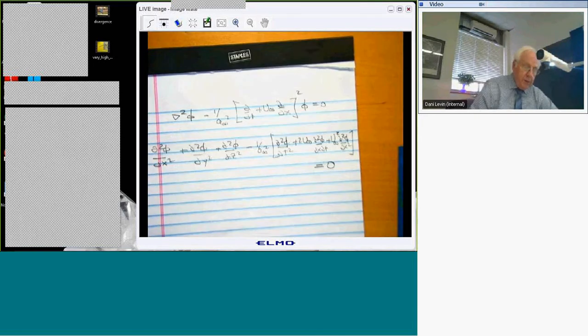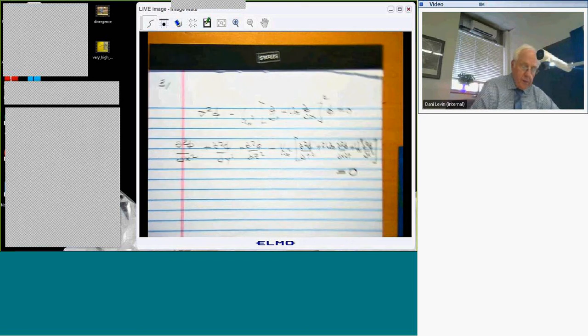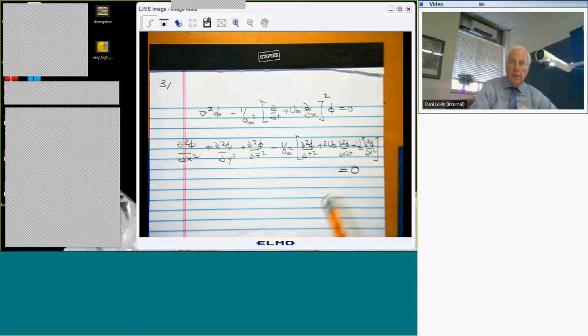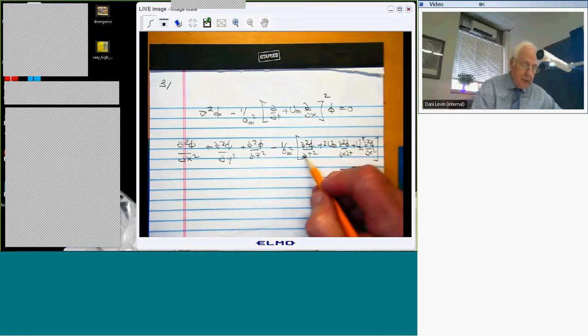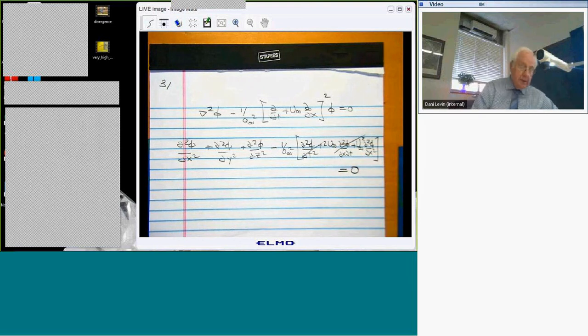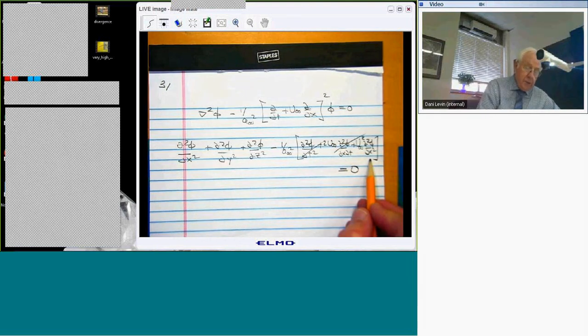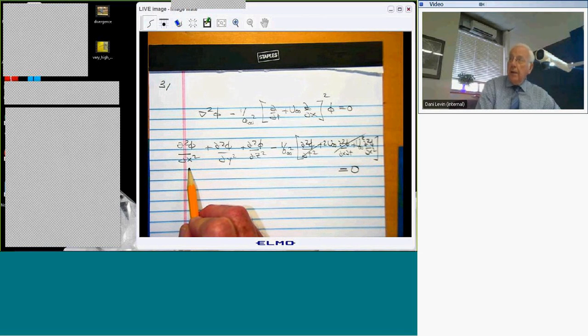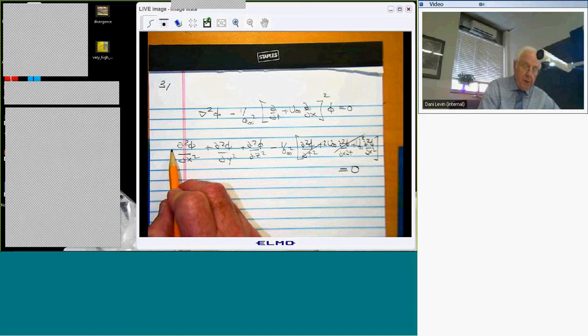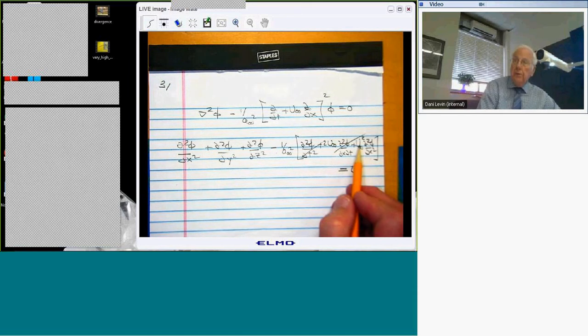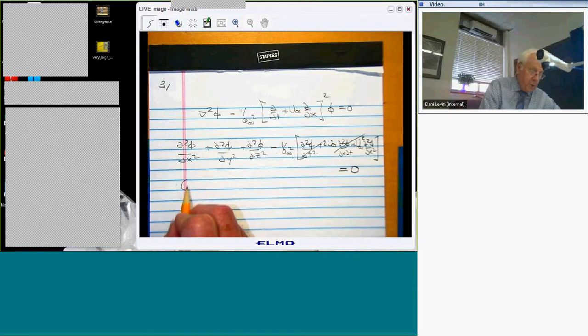And as I mentioned, things really, in some sense, get most severe in terms of this theory breaking down for steady flow. So just for the moment, we'll come back to unsteady flow, but let's look at steady flow, which means these terms go away. Right? So now this term and this term are mathematically alike. They're both second derivatives with respect to x. This one has a coefficient of 1, and this one has a coefficient of minus U infinity squared over A infinity squared, otherwise known as 1 minus the Mach number squared.